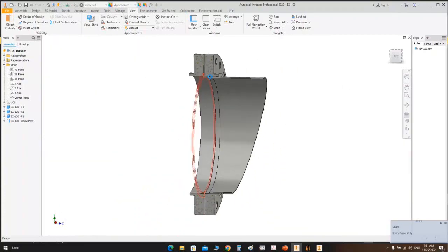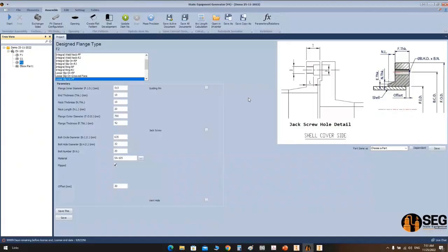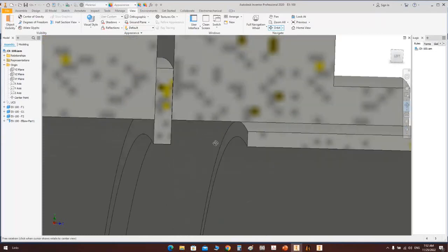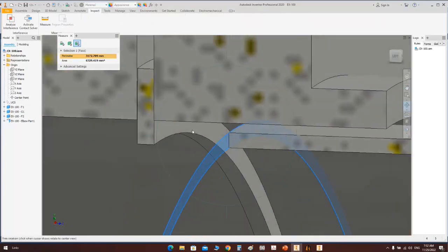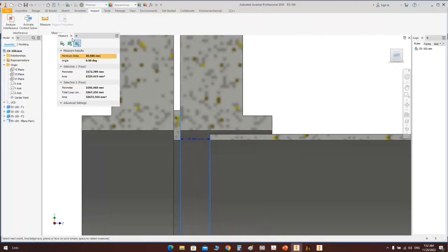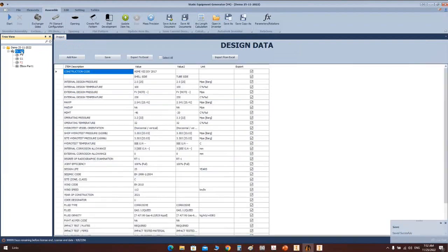Okay, you can figure that the offset becomes here. We make an offset of this flange. If you take a look at the image here, that's the offset, from the next element to the facing of this flange. So if you take a look here, you have an offset with that value, which is 20 millimeters. If we measure the distance from here to there, it's 20 millimeters from here to there. Okay, so by controlling this offset like that, let's add the next element for the elbow.